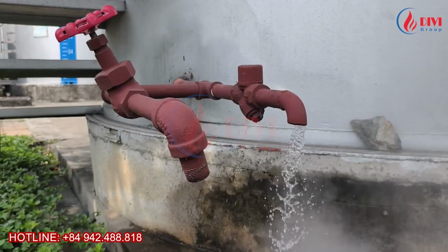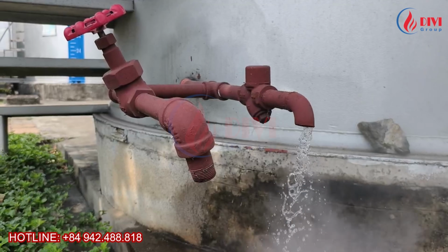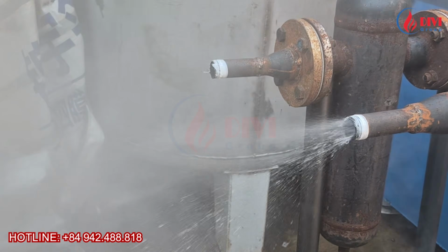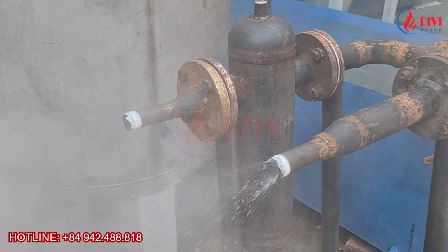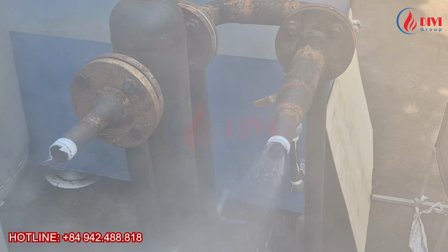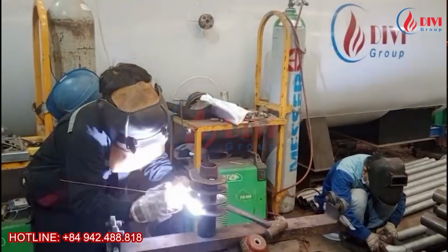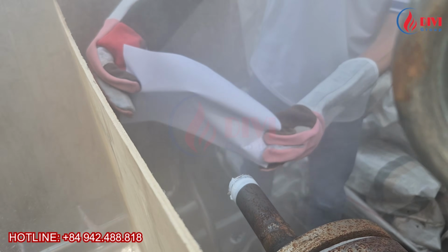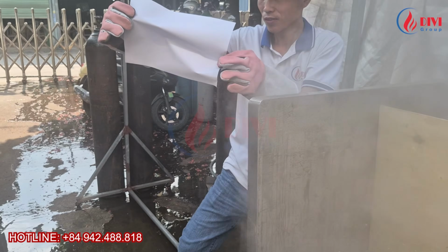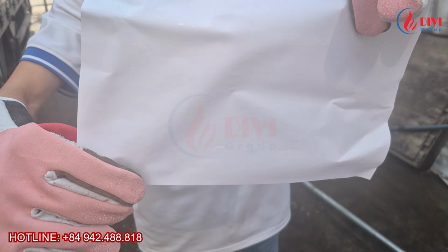If wet steam is not caused by chemical issues and excessive condensate is still present in the system, installing a steam separator can significantly improve steam dryness. We recommend using a multi-cyclone or spiral-type steam separator capable of achieving moisture removal efficiencies above 98%. A simple field test is to blow steam onto a sheet of paper. If the paper remains dry, the steam quality is generally acceptable.